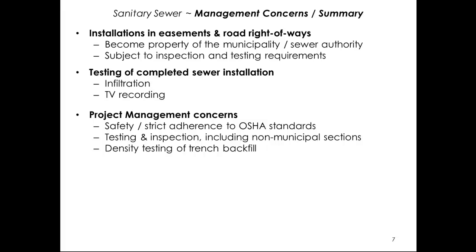From the project management side, working in trenches is very hazardous, and absolute conformance to OSHA safety policies must be maintained. The non-public sections of the pipe also need to be inspected for the benefit of the owner and contractor's quality control. And proper compaction and testing of all trench backfill should be required to prevent settlement gullies at a later date.